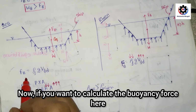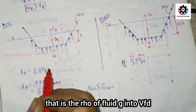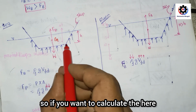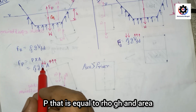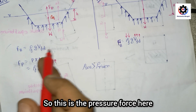Now the buoyancy force here is rho of fluid g into V_fd. If you want to calculate the pressure force, it is P into area, and we know P is rho g h, so the pressure force is rho g h into area.